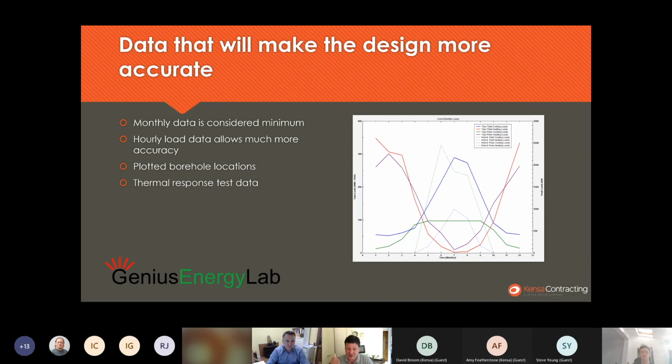And then finally, thermal response data. That's going to be the opening topic for next week, to talk about how we actually capture the physical properties of the ground. I'm going to show you how that process works. But what that does is, rather than having estimates in those boxes in GLD for undisturbed ground temperature, conductivity and diffusivity, we've got measured values. And almost always we are measuring higher values than you would prudently assess from the desktop.